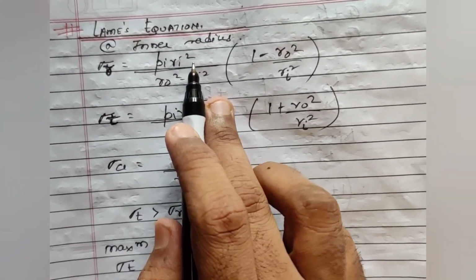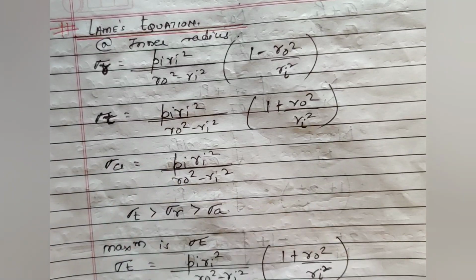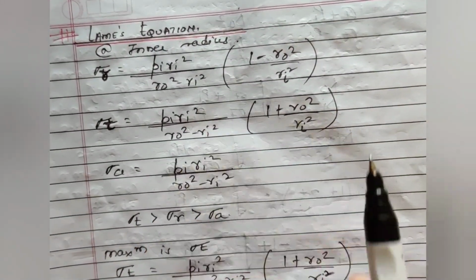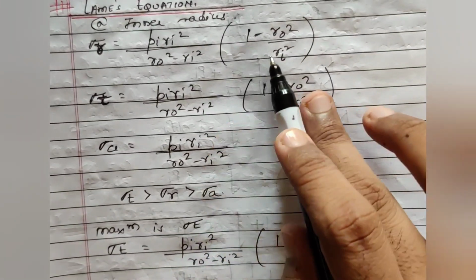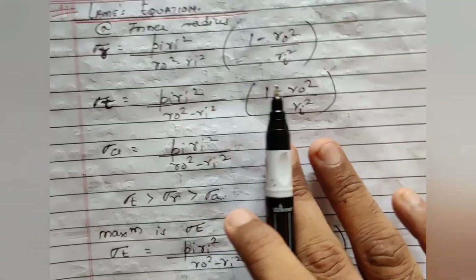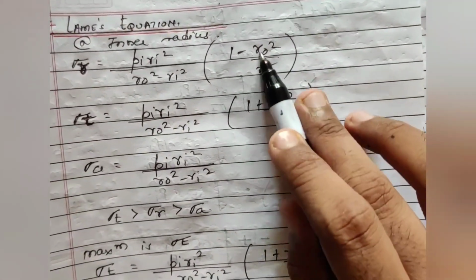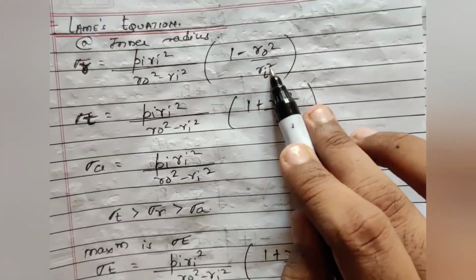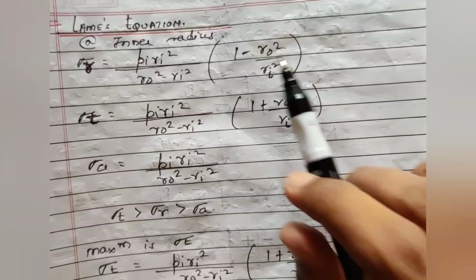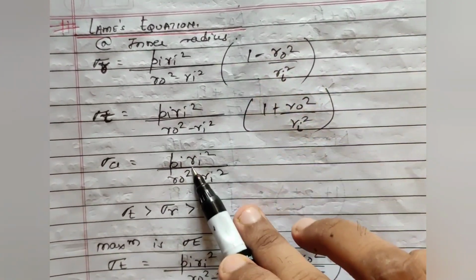So using that theory here, now these are the three principal normal stresses which will be induced at the critical point, which is the inner radius. In terms of the inner radius we have written the equation. So everywhere wherever there was R, we have replaced it by Ri. This was, if you remember, R square by R square, so there it becomes Ri. Here also it was R square, so it becomes Ri. And axial was constant. So these are your three equations.